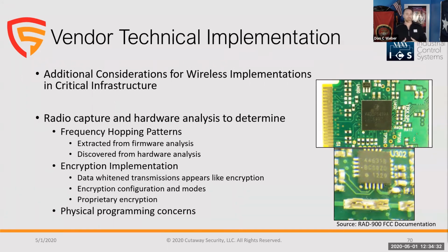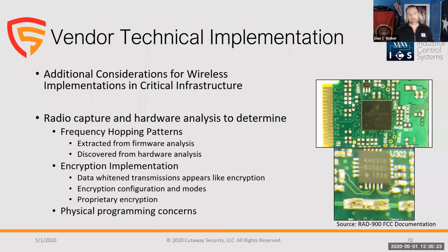I start looking at these devices, start pulling them apart, seeing if I can understand frequency hopping by pulling the information from the microcontrollers, seeing if I can understand if they have certificates stored insecurely, and even trying to determine whether or not I can predict their certificates. If there are cases where vendors have picked 10 certificates, as an example, deployed them to all their devices, and then pushed it out, and there's no way for vendors or for customers to update those certificates, but all of a sudden they become public. So understanding that will help everybody understand the risk around implementing some of these technologies and addressing it with the requirements or compensating controls. But we wouldn't understand that without security research into these devices, actually pulling them apart, actually seeing what their implementation is.